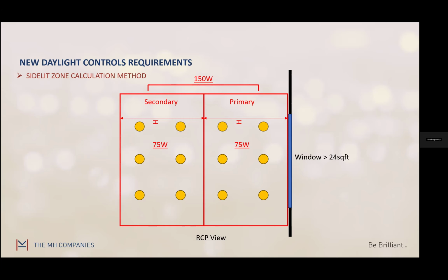If you think about that in a classroom application, where you might have a dozen classrooms, each classroom has upwards of maybe three circuits that you have to switch via that timer switch. That could be a lot of clocks to maintain, because those are all going to be individual clocks. And there's inevitably going to be some time drift that someone's going to have to go through and adjust. So yes, you can do it, but be mindful of the application.